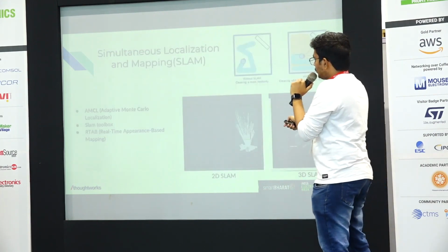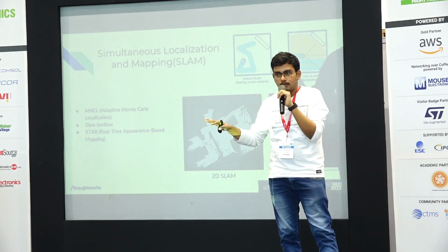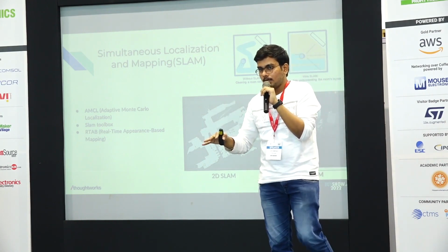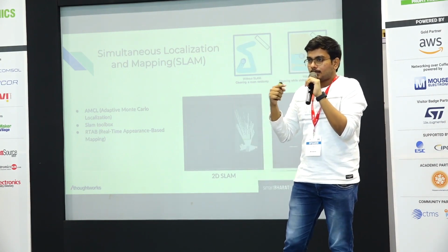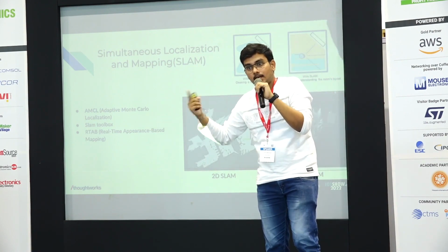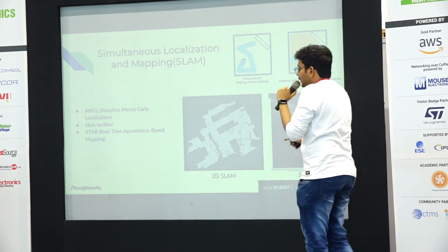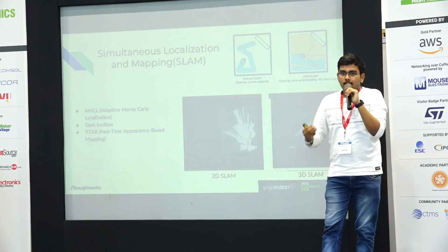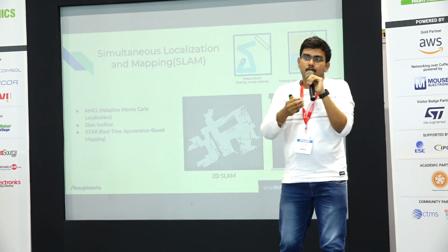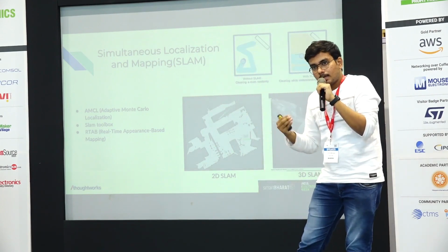So moving on to the next slides. Now we are able to perceive the data in the environment. We know where the obstacle is, whether it's free space or whether there is an obstacle in front of it. And because of dynamic transform, we can tell the bot that it is this much distance from this particular place. Now, the next important thing is we need to create a map. A mobile robot doesn't know the environment it moves in, such as where the restroom or the entrance is. So we need to create a map so that the bot can use it for navigation.